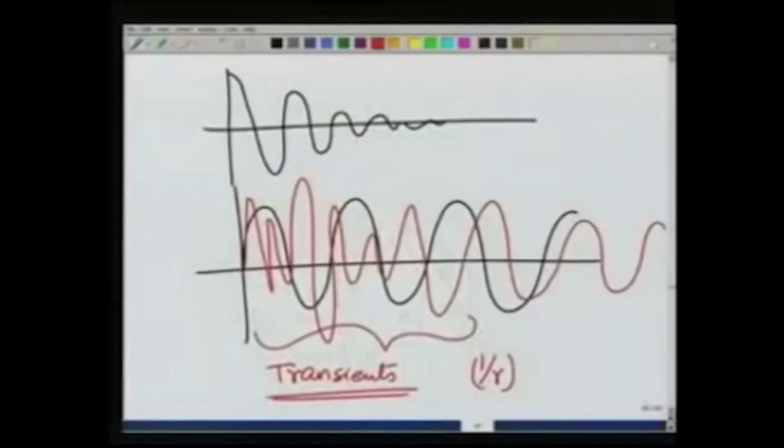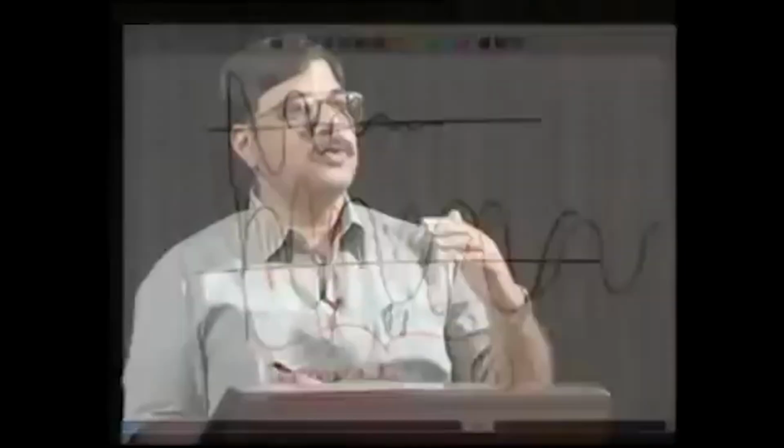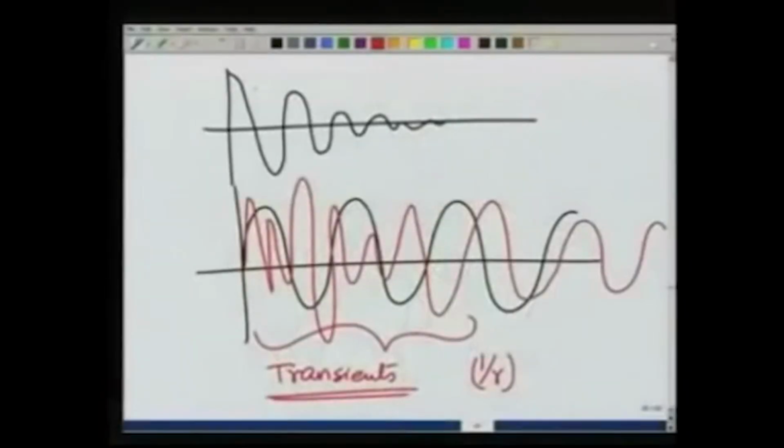However, what you notice is that the transients could give you a very haphazard motion. Take an oscillator, force it with a certain frequency, and you will see initially it is moving back and forth in no regular pattern, and those are the transients. After some time, these transients, or the homogeneous part, die down, and what you see is the steady state solution. This is one thing that I thought I should mention.